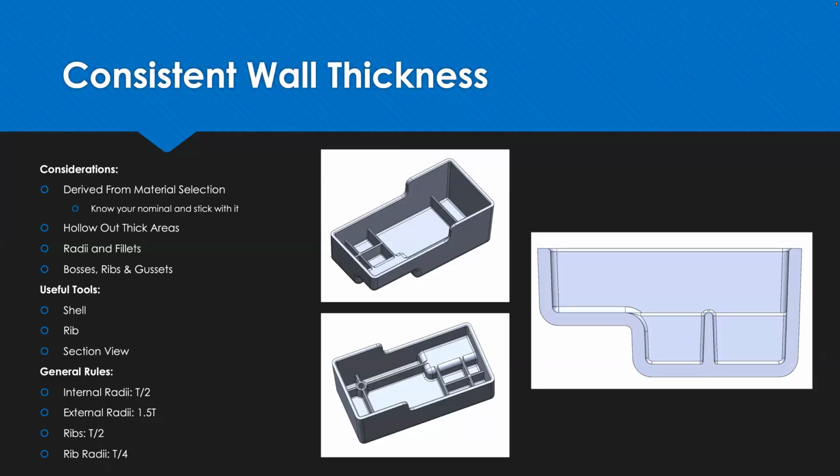But you can definitely, there's a lot of best practices with injection molding, and then there's a lot of cheating a little bit here and there. So you can get away with certain things, but you can't get away everywhere all the time. You have to pick your battles. Hey, this feature is not ideal to make, but it really needs to be like this, and it's hard to do any other way. Then it's like, okay, well, maybe you can cheat that one feature, but you don't want to cheat every feature on every part. It just becomes too difficult to mold at that point.